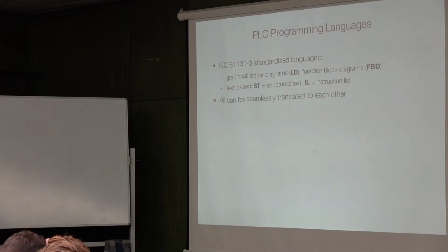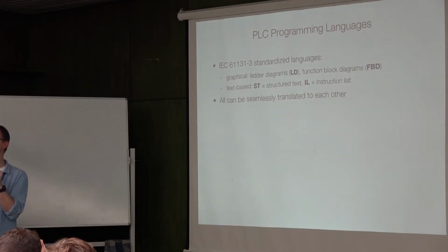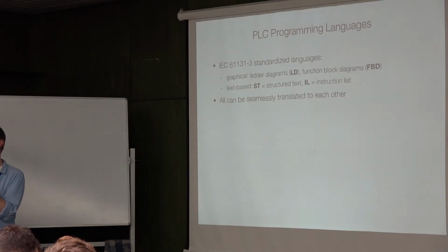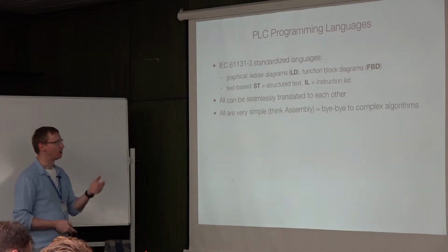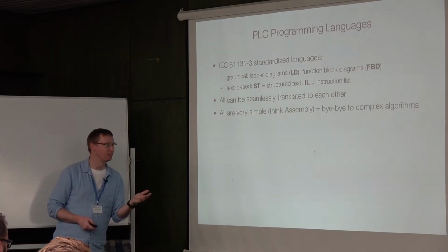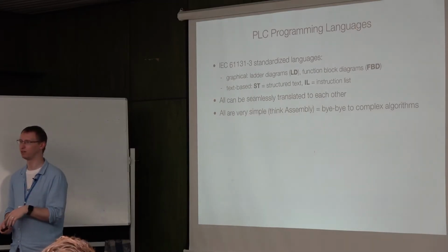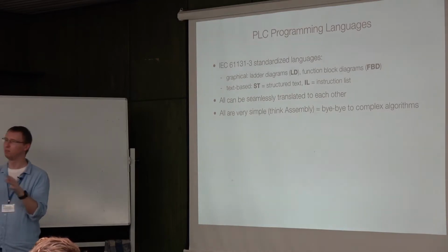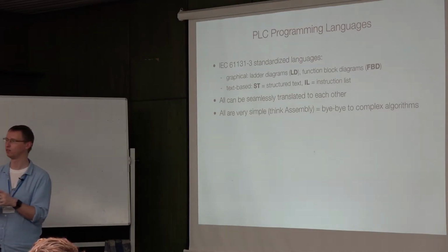And all of them are basically assembly languages, meaning you have an instruction like add 2 numbers, and then you provide the operands, like which 2 numbers you want to add, and the value is stored somewhere, and maybe propagate it along the program flow. And all of them are extremely simple. That means you can say bye-bye to any complex algorithm. Complex, I mean really anything beyond LQR, and maybe very simple of those analytical solutions.